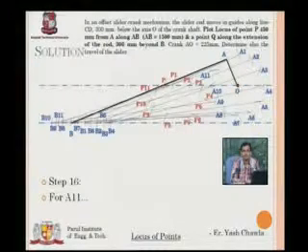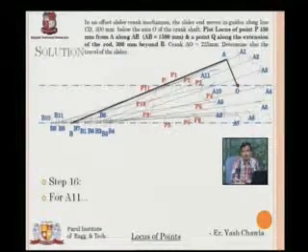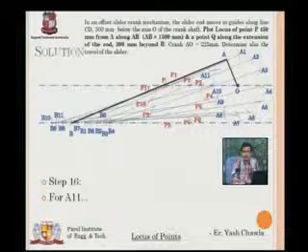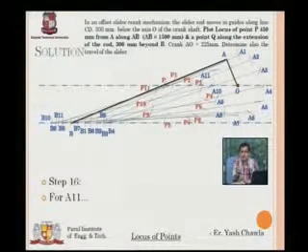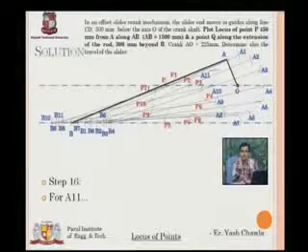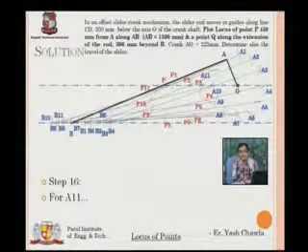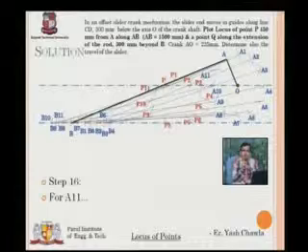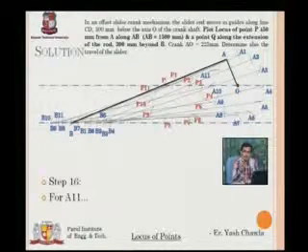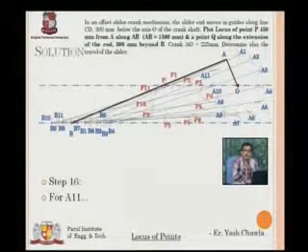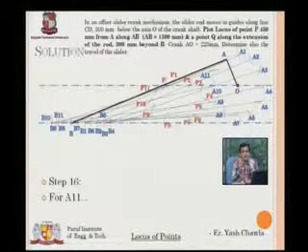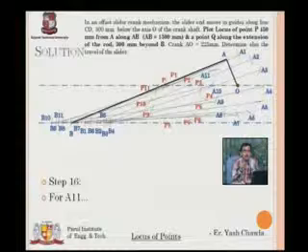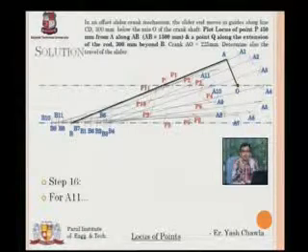So again we can see that we have all the points in association with the position of the slider, the position of the connecting rod, the position of the crank. Right from A till A11 we have crank positions, for the slider we have different positions from B to B11, and at the same time the position of P is determined by the red markings or the arcs which are cut on the connecting rod from P till P11.